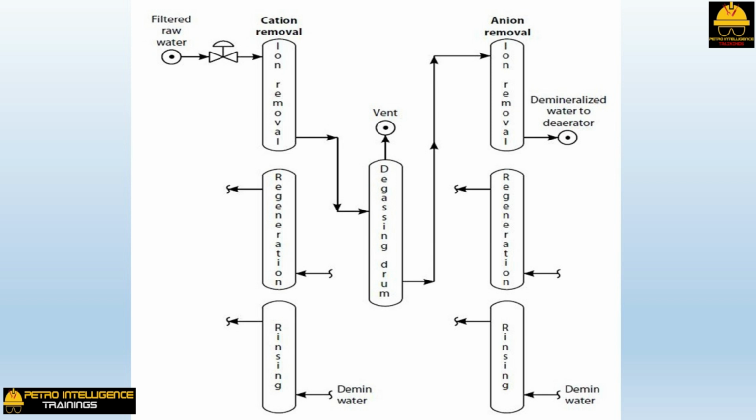It is important to avoid stirring up the resin during the regeneration step. The main objective of the regeneration step is to leave the purest resin at the bottom of the vessel. This will then polish the downflowing water when the bed is returned to its ion exchange service. A slight back pressure, using air, is typically employed at the top of the beds to hold the little beads in place during regeneration, and works best after first draining the bed down by about 1 foot below the top of the resin bed. It is also possible to lose the beads from the ion exchange vessels during the regeneration and washing steps if the resin beds are not held down properly during this step.